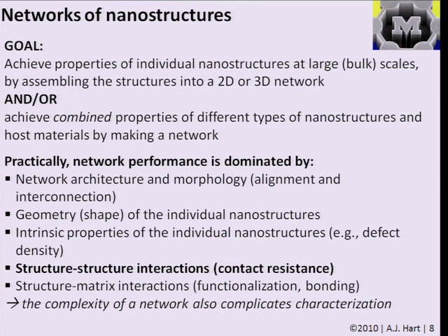Comparing nanorods or nanotubes to nanoparticles, the behavior, say, of conductivity as a function of the volume fraction is going to be very different if you're adding pieces that are very long and narrow and sort of hooked together easily to individual particles. Also, the intrinsic properties of the individual structures are important. We'll see cases where the transport is dominated by the characteristics of the structures, and cases where the transport is dominated by the contacts between the structures.